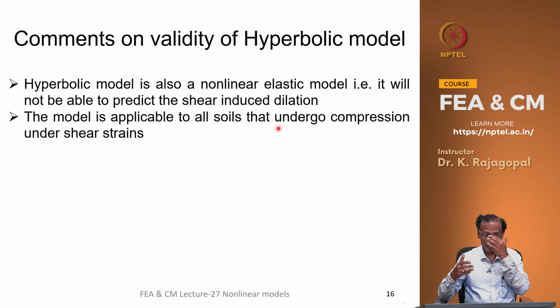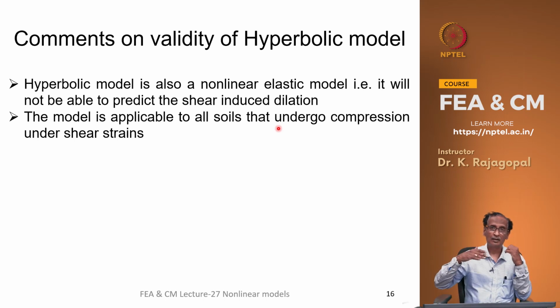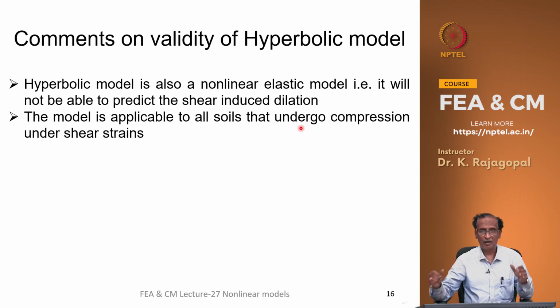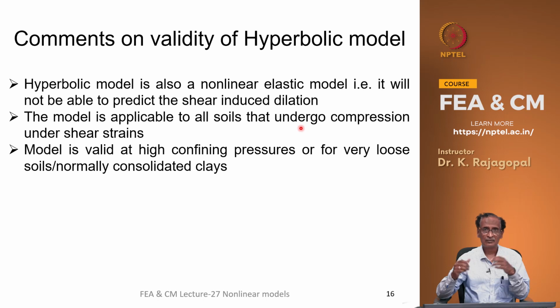So, we cannot really represent dilation, the shear strain induced volume expansion, and so we can safely apply this model to all the soils that undergo compression, that is our loose sands or normally consolidated clays, or even dense sand with a very high phi, but at a very high confining pressure, the soil will only undergo compression because of the suppressed dilatancy.